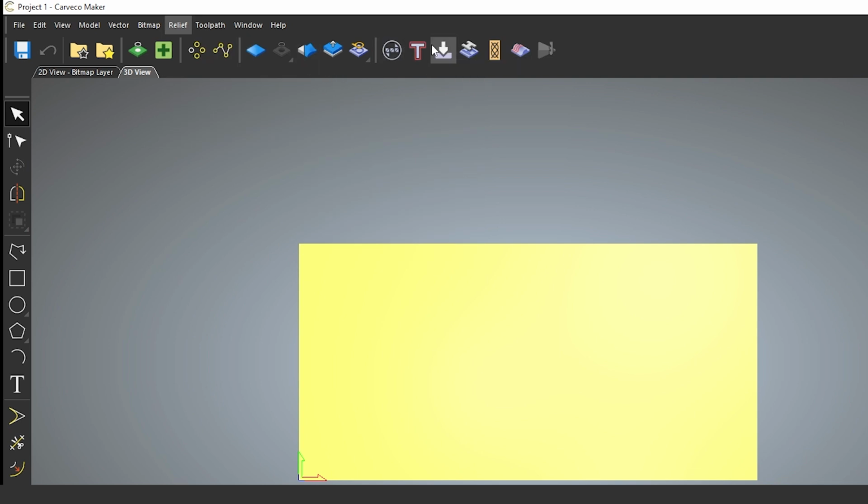And finally we get onto the toolpaths section. This is ultimately what we will use to generate the various toolpaths for doing our profile and pocket cuts and various things we will need throughout the series. We will see that simulation is grayed out at the moment, again because we have nothing on our work area, we can't simulate a job. But this relates back to the setting we adjusted at the start with the resolution. Because we have set it to a high resolution, our simulations will come out nice and crisp.